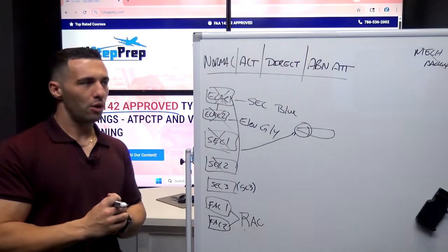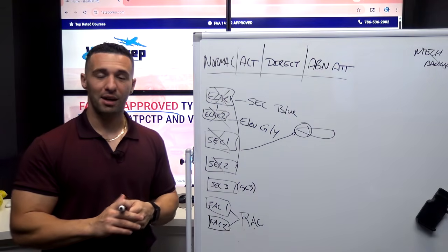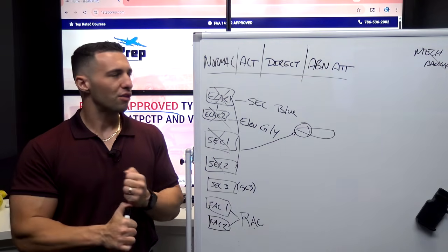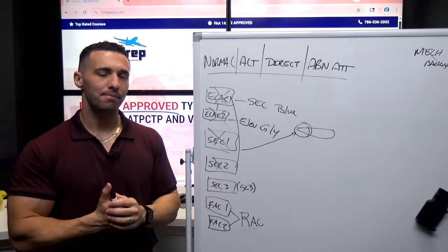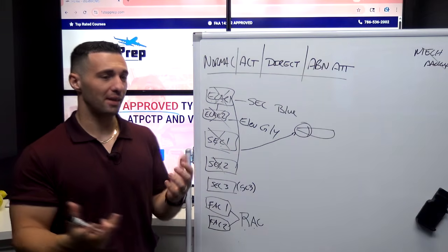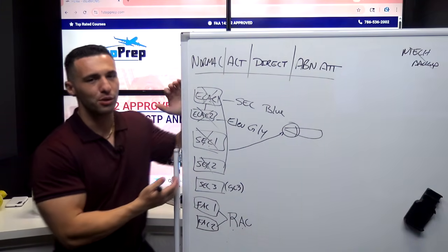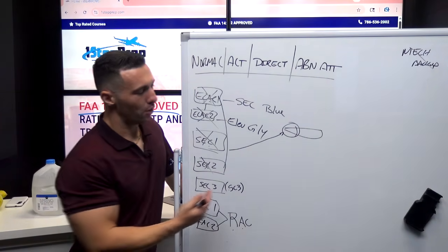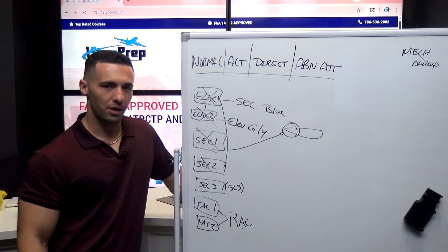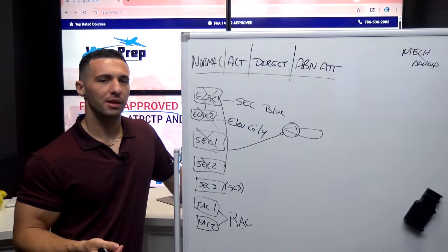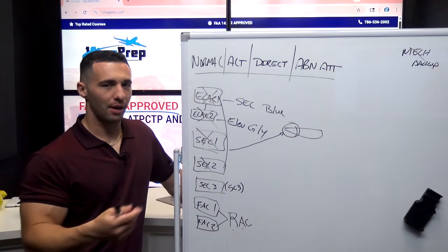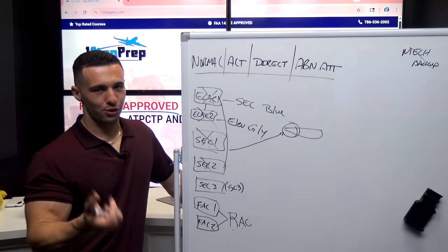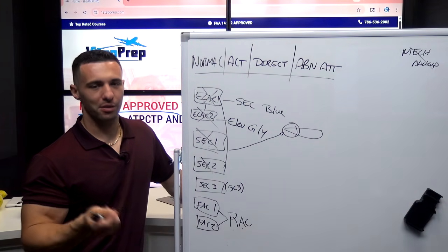Now, mechanical backup for the most part is there and designed to help you keep the blue side up, to keep flying, so that hopefully at some point somebody can do some kind of a reset that'll reestablish at least one of these computers. And if I can reestablish at least one of these computers and restore pitch control via the elevator here, then I will have ultimately regained a law, which would be alternate law, that would later turn to direct when we put the gear down with the autopilot off, so on and so forth, right?